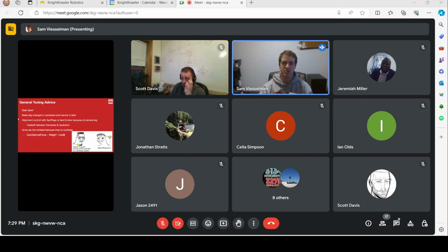We also like to, when you're doing the tuning, make big changes in your KP and narrow down later. And so it can be a huge waste of time to start with a value that's way off and adding 10% to it, add 10%.